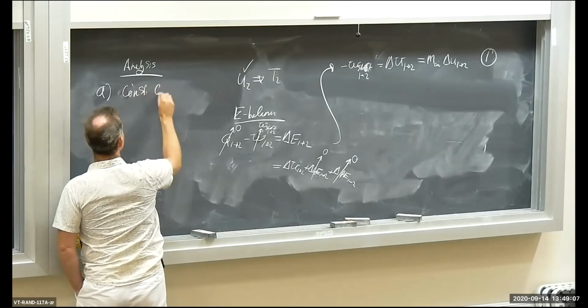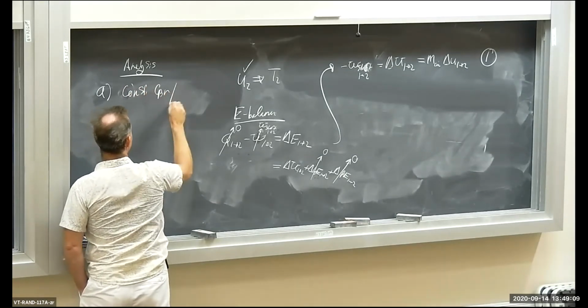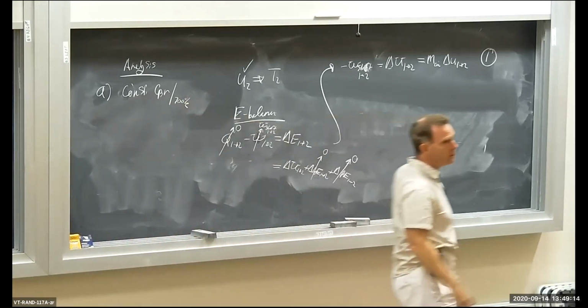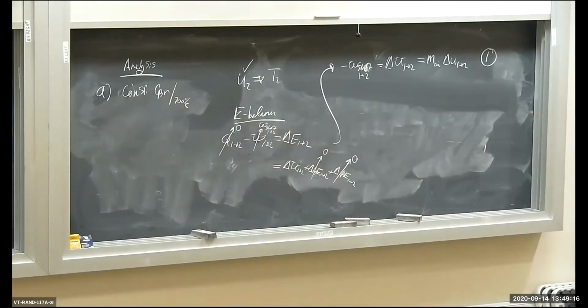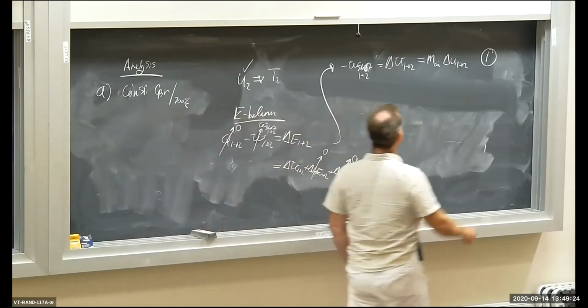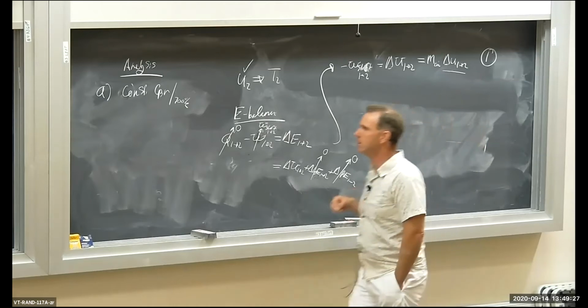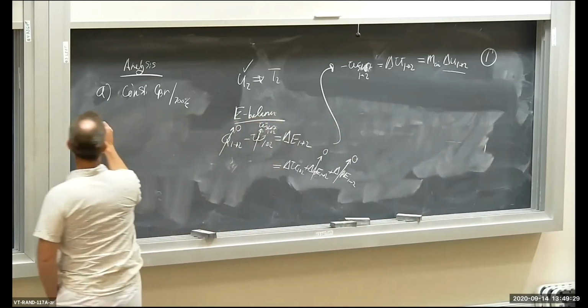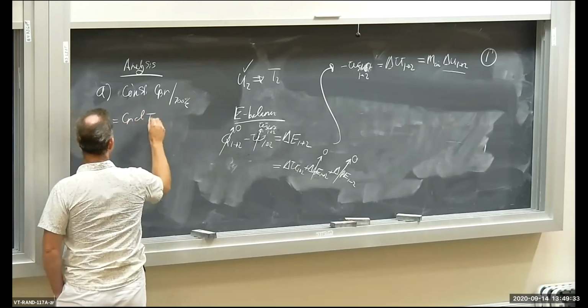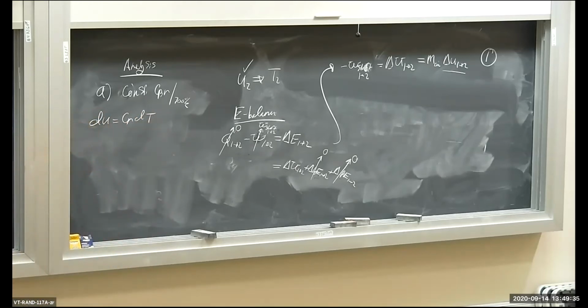Constant CP and CV evaluated at 300 degrees Kelvin. That's how we're going to solve for T2 for part A. So the problem splits up at this point. Okay, so let's recall from the property relationship, du is equal to CV dt. That's a property relationship that we derived last time.